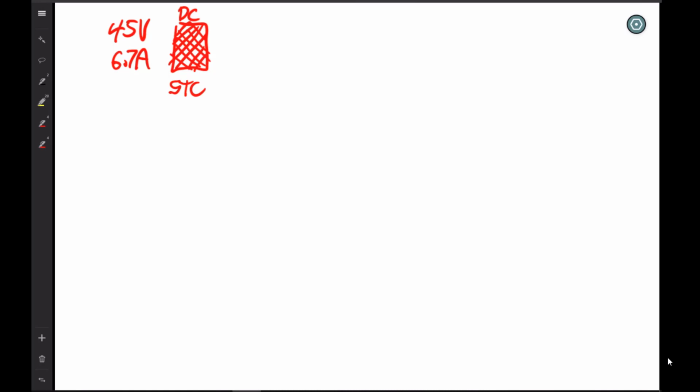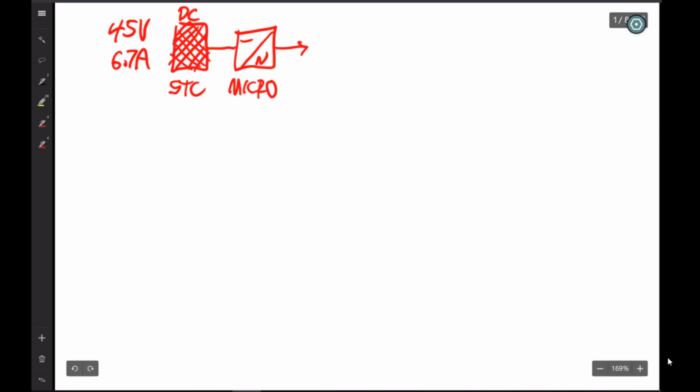So to get that power useful out of our outlets, your outlet is 120 volt and so forth, we need to convert it, and we use an inverter that takes DC in and creates AC out. And this is the most basic system, and it's called a microinverter. Microinverters are small. Think of the size of a book mounted to the back of the module. And usually they're 1-for-1. So if you have a module, you have a microinverter.